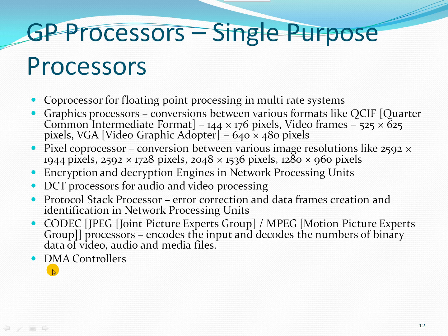And the last one will be the DMA controllers, that is the direct memory access controllers. Since we need to use the processors for the data processing and the real-time processing, we need to have these particular memory controllers as a separate and independent unit. So we need to use this DMA controller for the burst mode and very fast mode of data transfer between the processors and the memory units. We need to have these DMA controllers in all embedded and general-purpose computing applications also.